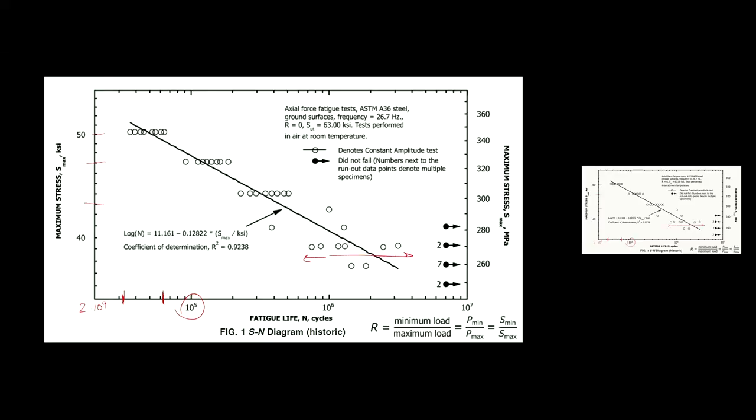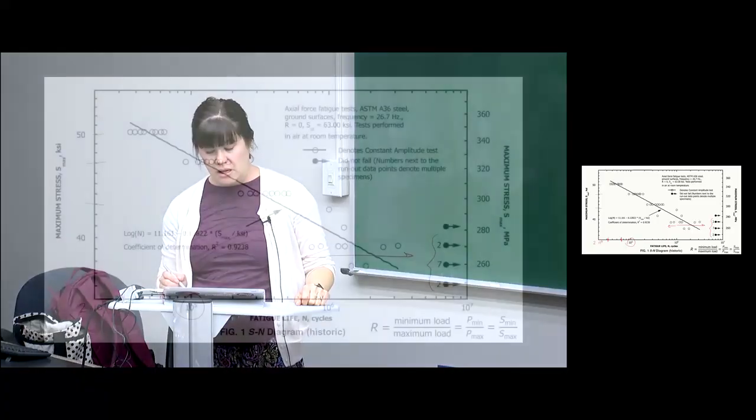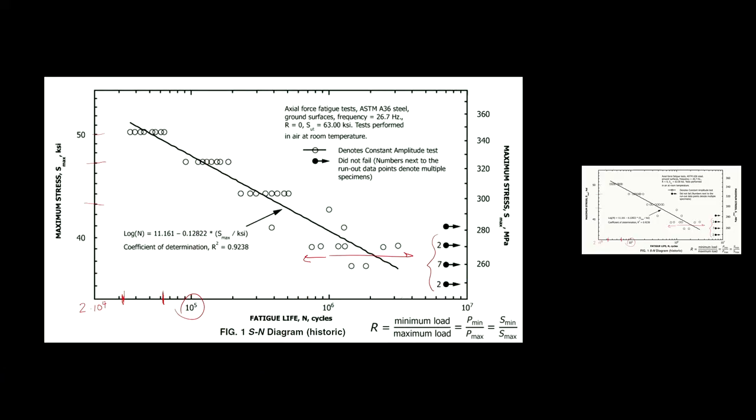And that's where we start to define something like an endurance limit for this material, because there were multiple tests that were beyond the definition of how many cycles we were going to go on this test, right? So if you go out to, let's say this is 1 million, so 2, 3, more than 3 million cycles here, and you're at 100 hertz in the lab, right?